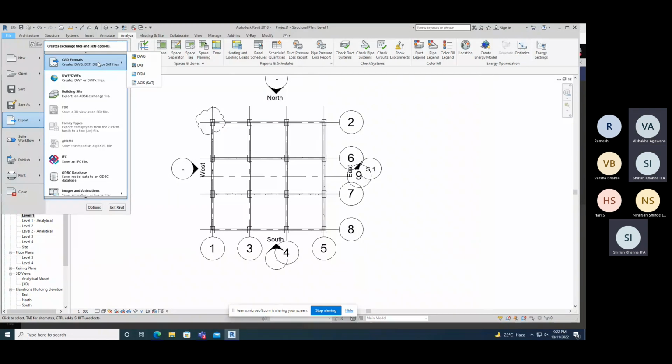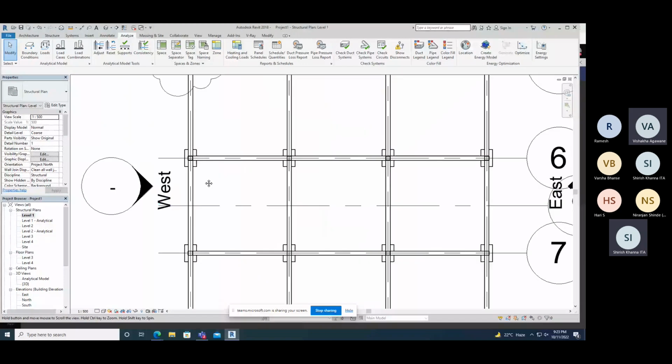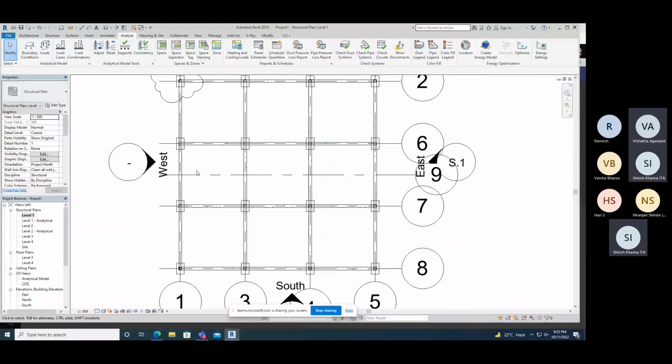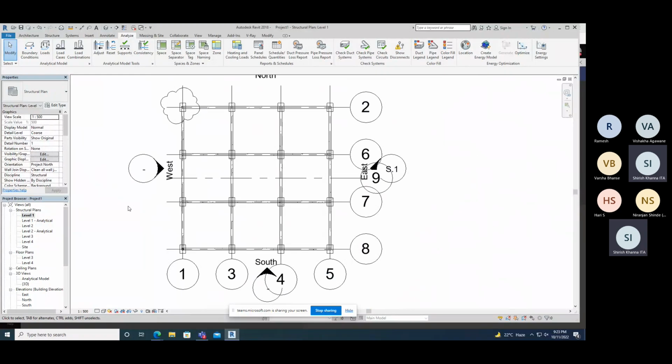Can we change the color of a line, say a center line, in visibility graphics? Yes, yes. The center line color in Visibility Graphics, see, AutoCAD also works like that. If we use red color here, in AutoCAD you will see it. You are using layers in AutoCAD. Yes. If you want to change the line type or line color, I told you, it is in the visibility graphics.